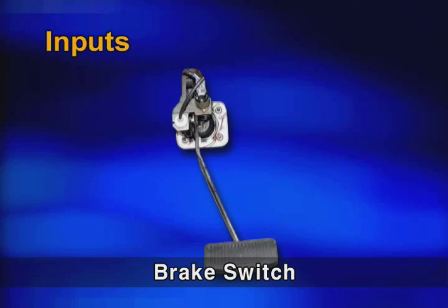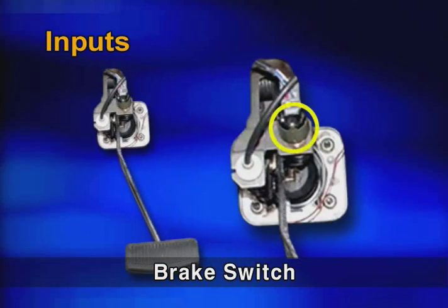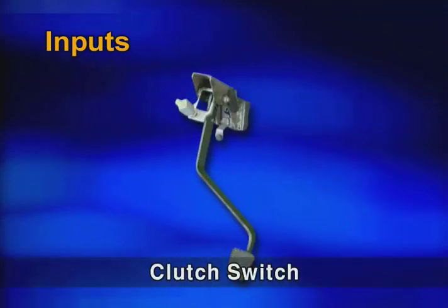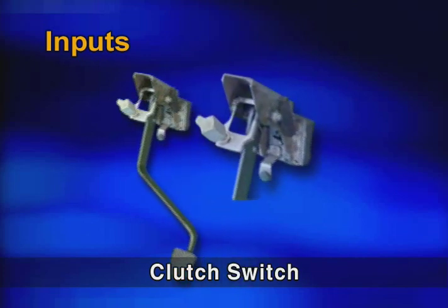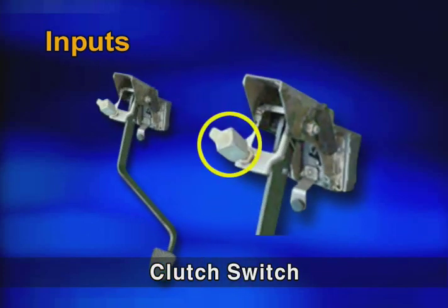the brake switch for sensing the brake condition of the vehicle and for sensing the adhering condition of the accelerator, and the clutch switch for maintaining the variation of the engine RPM in stable according to the operation of the clutch. The signals from these sensors and switches are inputted into the ECM.